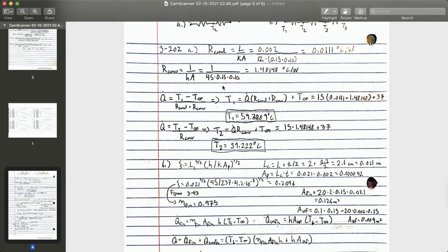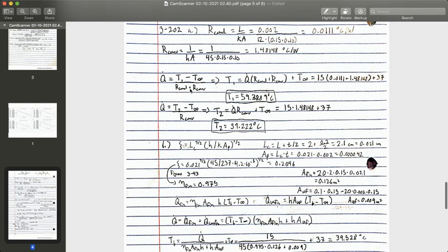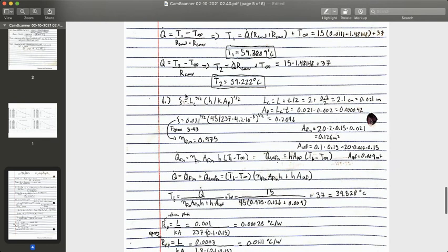So for the first part, we are going to go through and find our resistances as we're used to. Nothing new there. Gonna sum them, put them under the temperature gradient. This time we already know the heat transfer rate, so we're actually going to use that, rearrange this to find the temperature on one side of the circuit board, go through it with just a part of our system here to find the temperature at the other one.